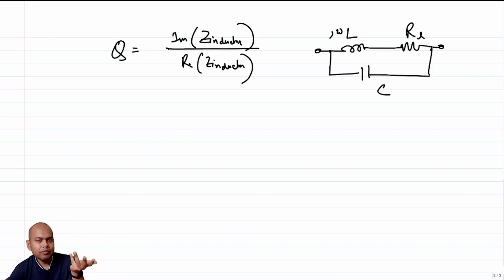Obviously, you would like your inductor to behave like an inductor. That goes without saying, which means that you have to ensure that you are slightly away, or significantly away, from the self-resonant frequency, as the need may be, right? So these are some of the things that you should keep in mind while designing an inductor.